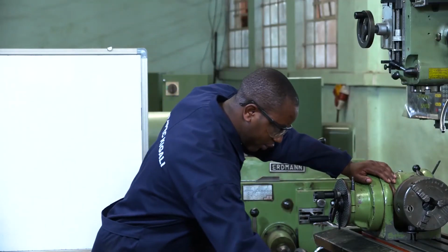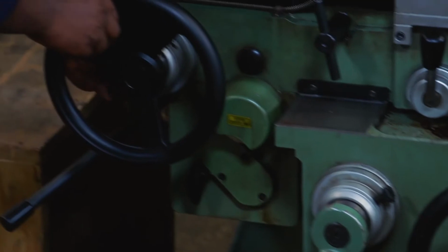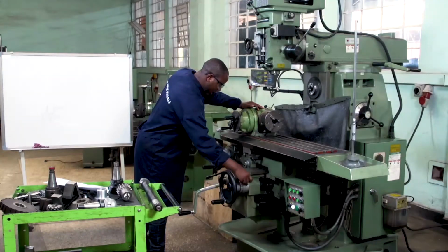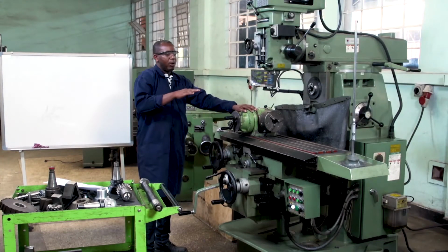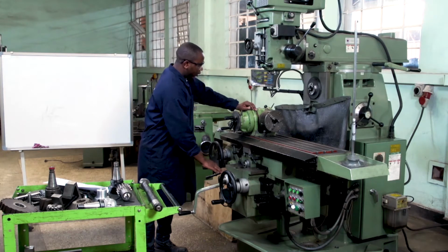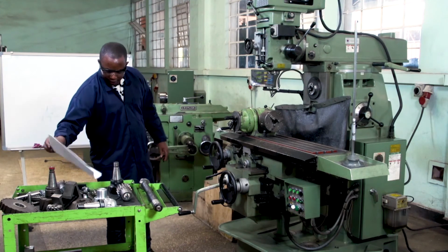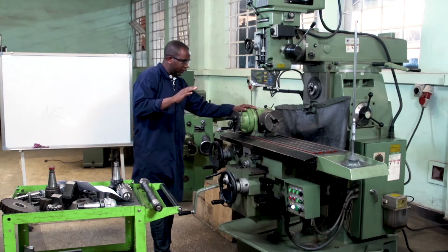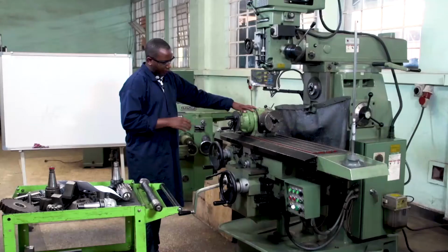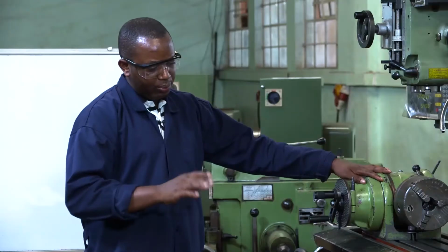On these handles, we can see the micrometer dials. Those micrometer dials are used to take the measurement. It's very important while machining because the amount of material being removed has to be specified by those micrometers. Of course, we inspect the measurement with the vernier caliper and other instruments, but you also have to use those micrometer dials when taking a depth of cut or counting a feed motion.